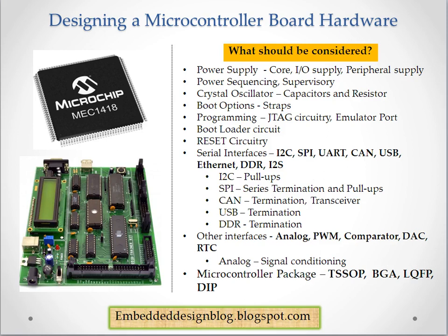USB: right now the industry is moving towards USB and ignoring UART because of the speed or the connector form factor. And then Ethernet, if you want to connect to a network. The advanced microcontrollers have DDR, like the Microchip PIC32s, and I2S is used for audio interfaces. So these are all the different interfaces that are there.